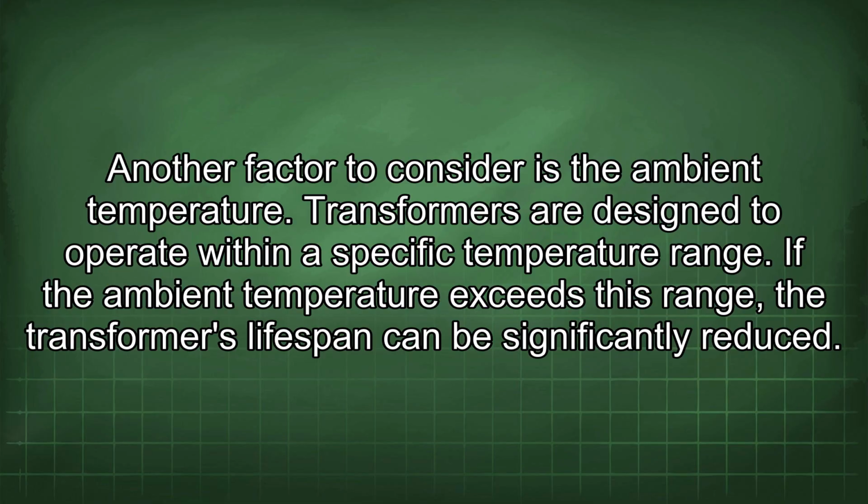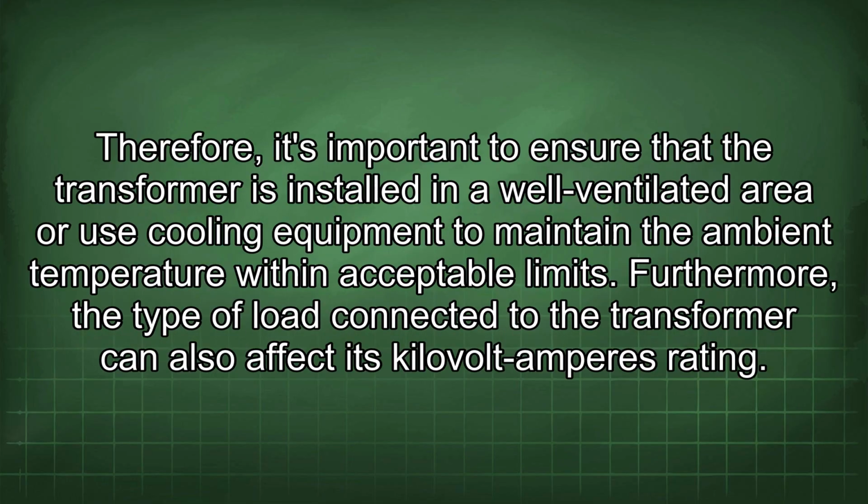Transformers are designed to operate within a specific temperature range. If the ambient temperature exceeds this range, the transformer's lifespan can be significantly reduced. Therefore, it's important to ensure that the transformer is installed in a well-ventilated area or use cooling equipment to maintain the ambient temperature within acceptable limits.